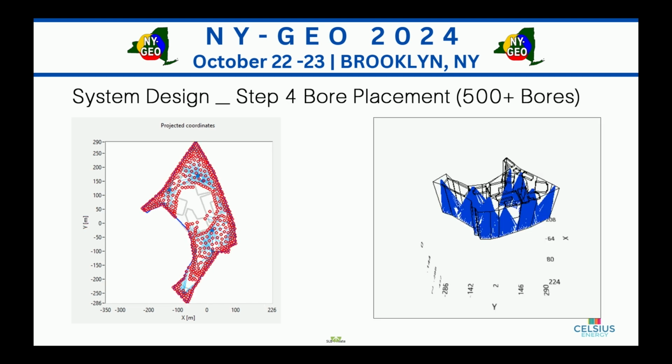As a fun element, I did an exercise and maxed out the software by reducing the spacing between the bores. We maxed this case out at 500 bores. The only limiting factor in this case is the space requirement, correct? We just could not physically fit more bores on this territory.